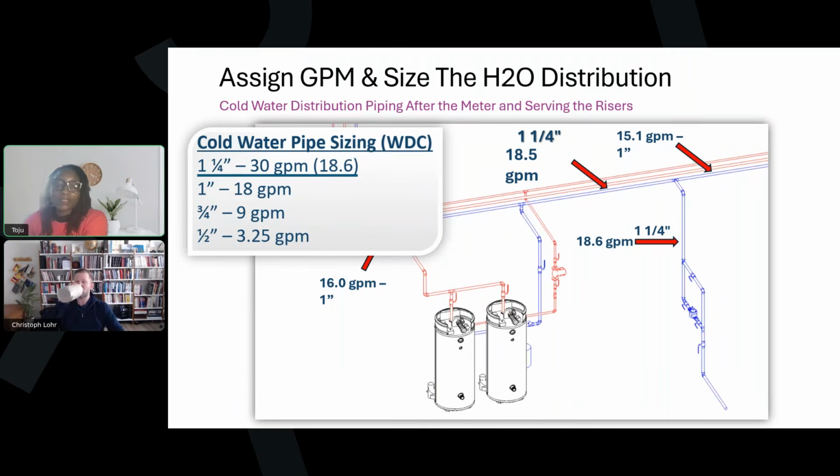Yes, but a lot of things are going on when you're increasing the fixture counts, depending on the section you're adding, or if you're doing just hot or cold water. For example, you might be adding a unit with a bathtub and shower compared to another unit with just a shower. The flow rates are different. And when you're increasing the number of units in the building, remember I talked about the probability of use dropping.